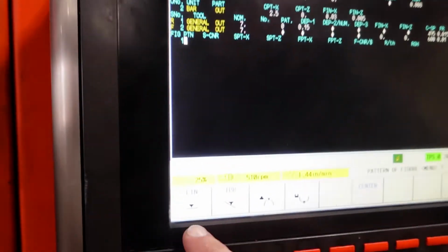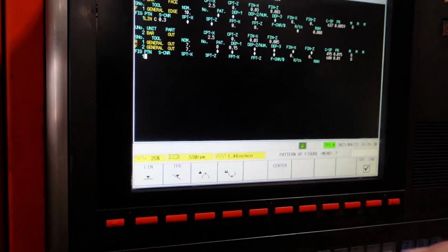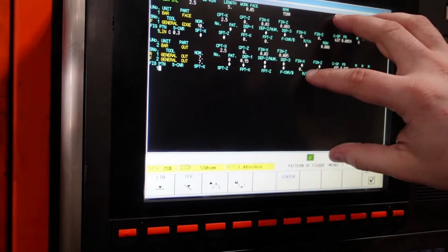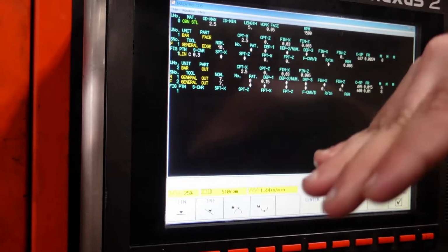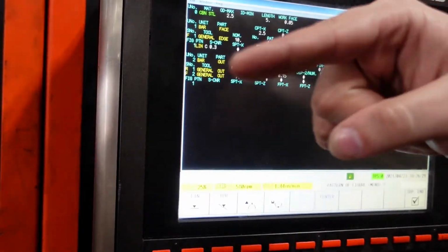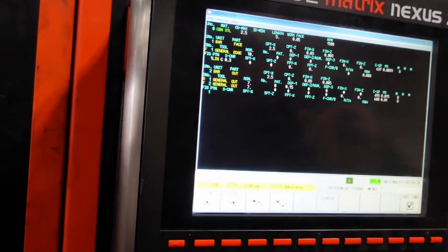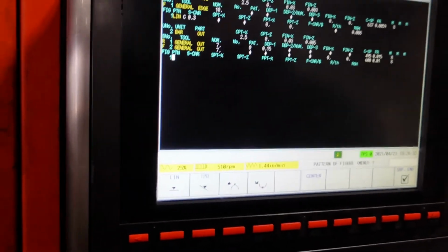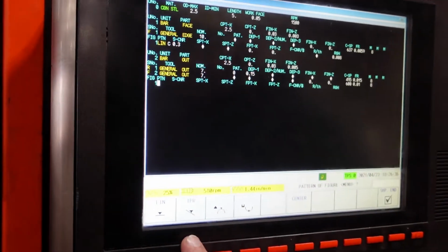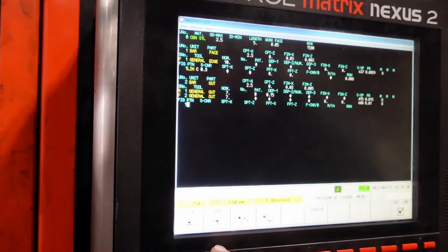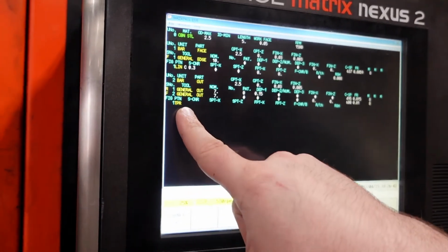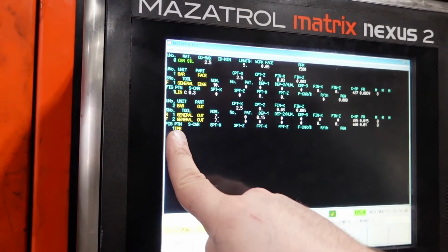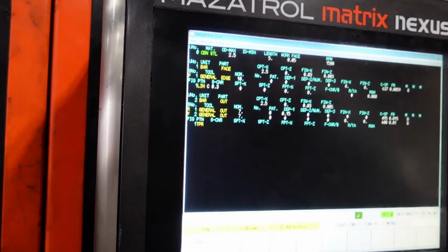will ask us, do you want a line or taper just like we did before up here? In this case, I want to have a taper because if this machine's been cutting for a while, and it's old, it'll have maybe 1 or 2 thou taper this way or that as it goes down the line in X and Z. Or if it has brand new ways, either way, you can use a taper line to accurately identify where you want to go. We will be using tapers later when we do compound angles to teach more interesting things.